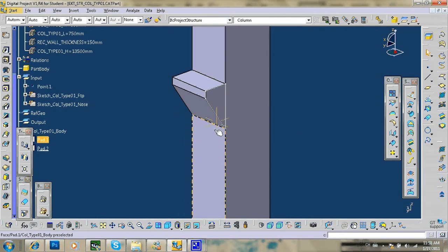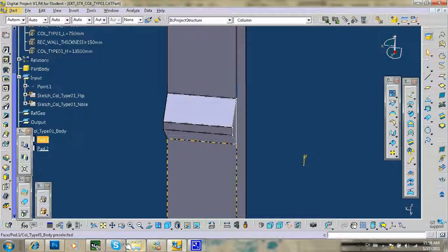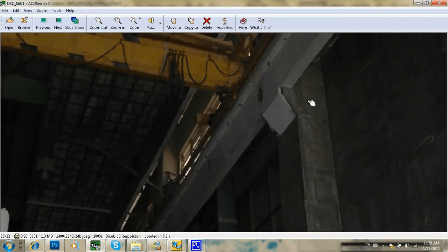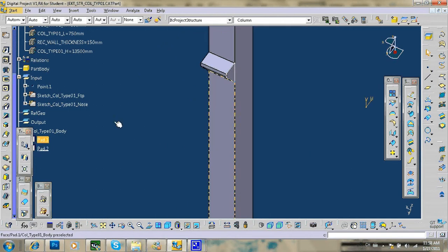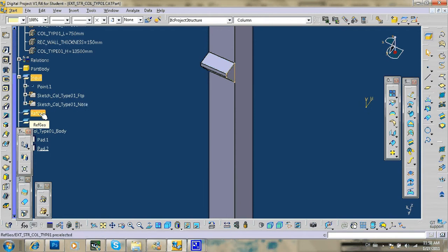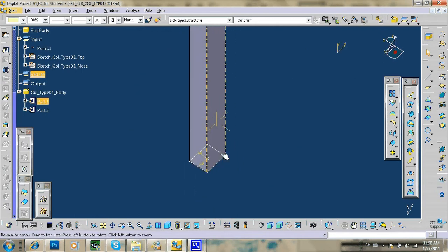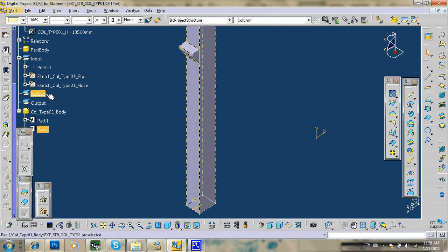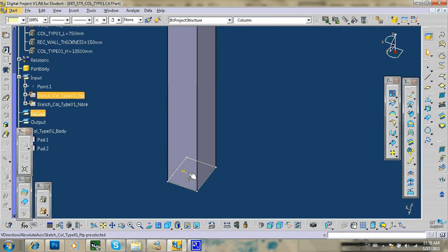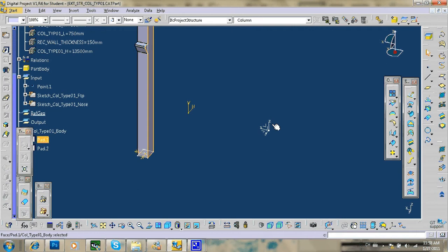Alright, and then we're gonna pocket out this middle bit, which is the gray part. So basically, what we do is we create a new sketch. Right click, switch back to no. This time I'm gonna use reference geometry as the geometric set to store the sketch. Okay. So we need to create a new sketch. The way we do it, we're gonna draw a sketch through the central point and parallel to this face, which is actually the Y and Z plane.